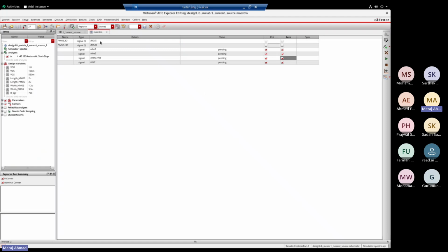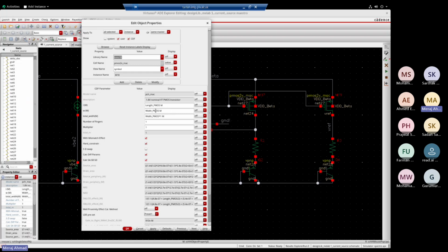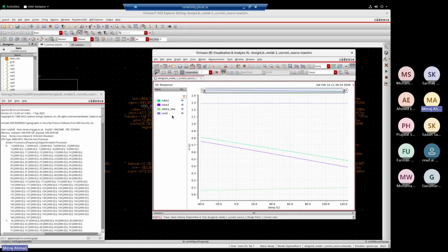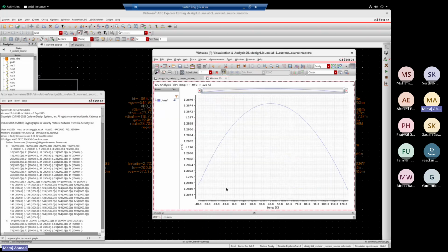In this, how it was made, the same unit element, NMOS, we have kept, and this is your reference. So you see this bell shape, 1.2 volt you can achieve. If you want more accuracy, then you do some curvature compensation, so it becomes an S shape.